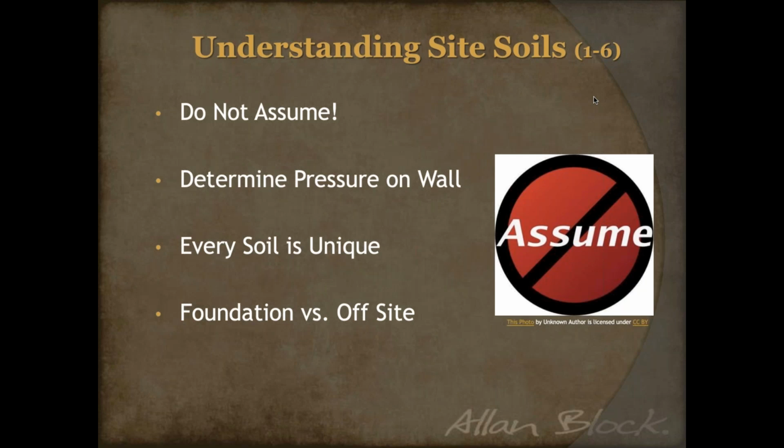So that's how we come to foundation versus off-site soils. If your foundation soils aren't good enough to be used for the wall design, you're going to have to bring in more granular off-site soil with a higher friction angle, or things like that, to make sure that the soils you use for your project benefit the design and make sure that it works.